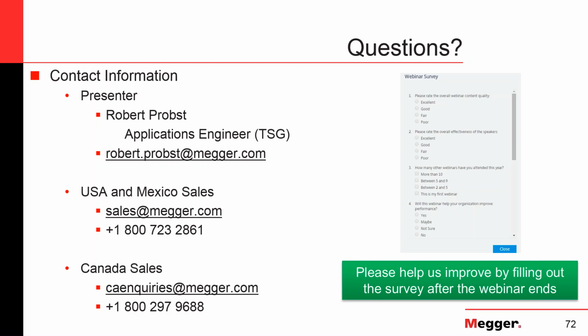What about using high current injection testing to test differential protection elements? You want to answer that, John? In principle, it's possible. You would do it the same way. Since primary injection testing is also single-phase injection, you can actually generate differential currents and prove that your protection scheme is working.